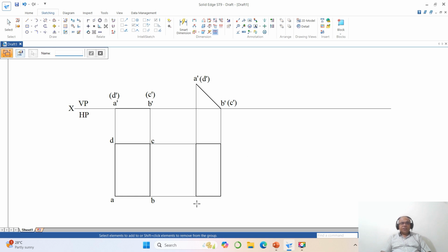Okay. Now I need to copy this. So go to move, enable copy, take A and you keep it here. Then similarly B, you copy it here, then right click, then go to move, again take this and copy it here, and after this you right click to cancel. Then again take move, select some arbitrary point and drag it till here and click the first button of the mouse. Do you want to continue? No, just right click on the mouse button.